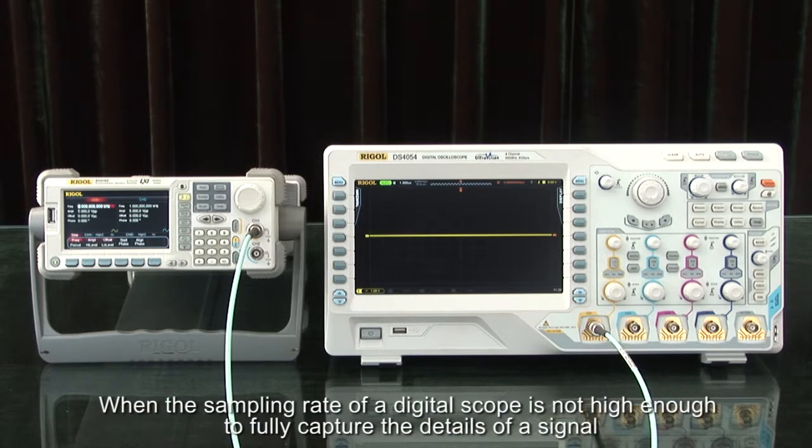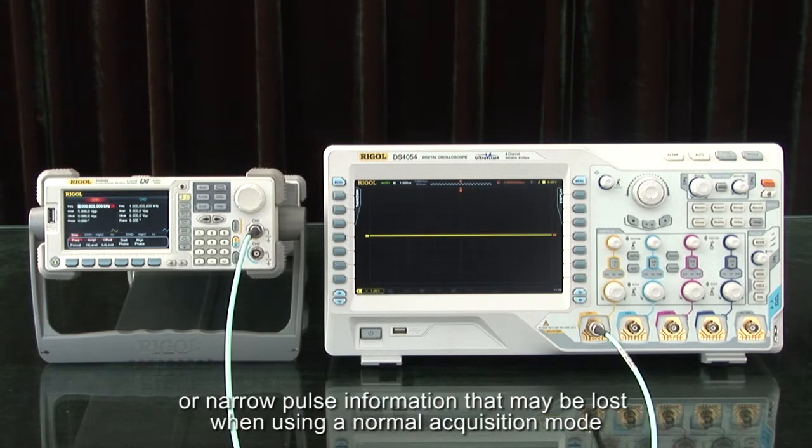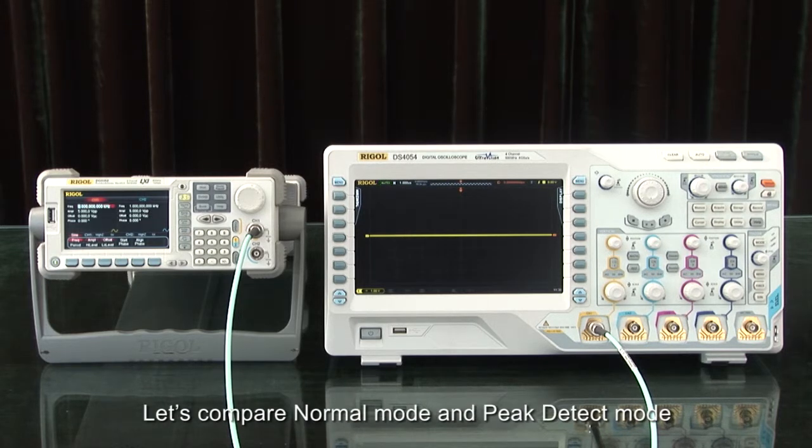When the sampling rate of a digital scope is not high enough to fully capture the details of a signal, you can use peak detect to help capture the envelope or narrow pulse information that may be lost when using normal acquisition modes. Let's compare normal mode and peak detect mode.